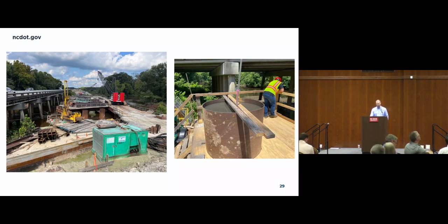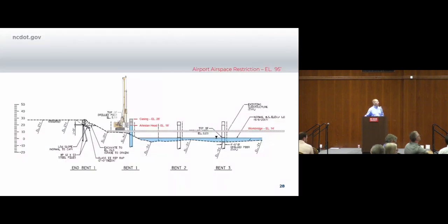But it was there. And I will say, in talking with Geotech, because I'm not an expert on this stuff, I was like, how does this get missed? As you may or may not be aware, they go out to do their investigation. They may be drilling from the bridge, right? So they're way up here on the bridge, 20 some feet up in the air, and when they're drilling, they're not necessarily going to notice that artesian head pressure that's down at a certain level below where they're drilling. Or if they're up in the embankment, they may not recognize it if they're not looking for it specifically. So it can be missed, and it was missed on this one.